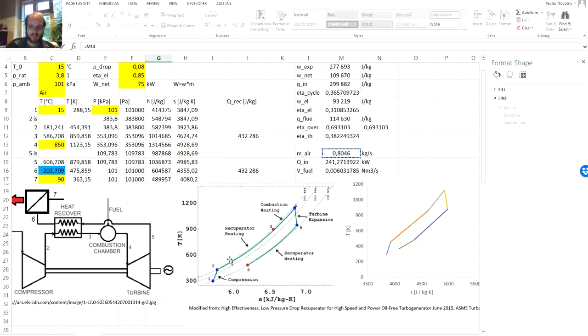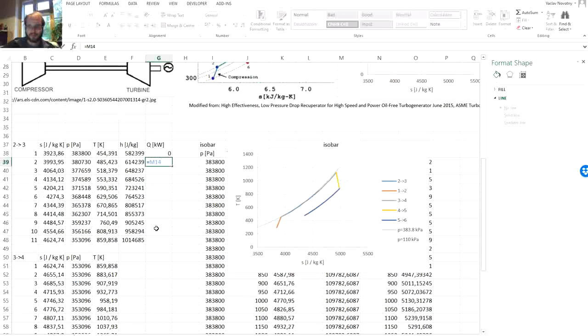In both cases, heating and cooling, we assume negligible addition of mass flow rate due to the fuel input, so just this mass flow rate of air multiplied by the enthalpy difference between this specific point that we have here and always the first point, because we are always referencing the heat transfer to the beginning of the heat exchanger.